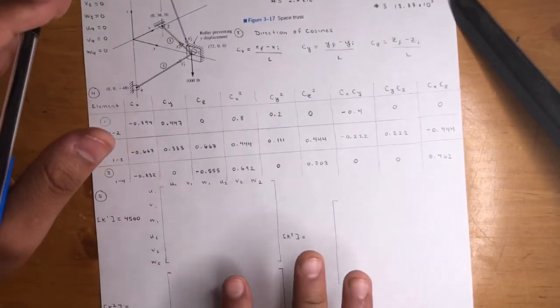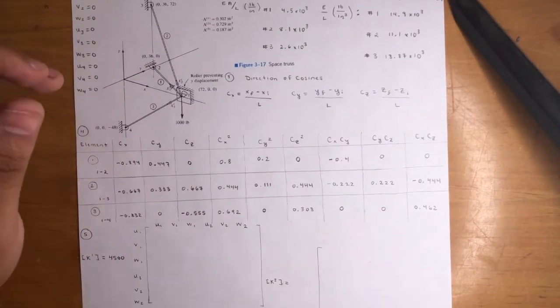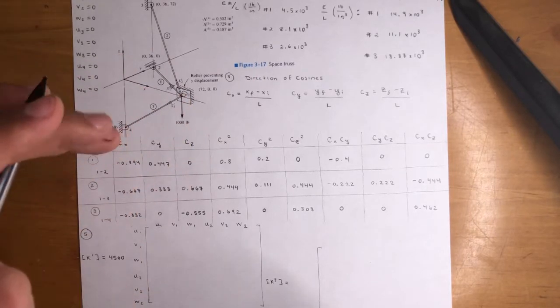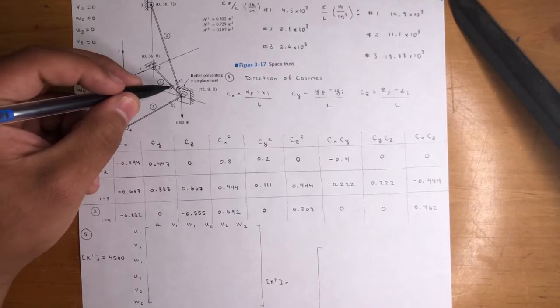It's not going to affect you when you make these little matrices and overall your big matrix. But when you get to the stresses in each element or forces in each element, it's going to ruin your signs. It's too much to explain, but just point is,